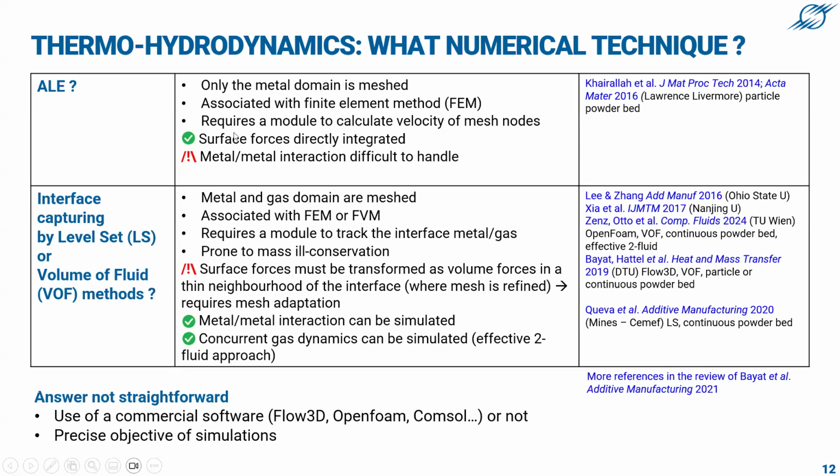The advantage of the ALE is that only the metal domain is meshed, which is good. But of course, metal-metal interaction is difficult to handle. The contact matters. So to treat instabilities of keyhole, for instance, is not very appropriate.